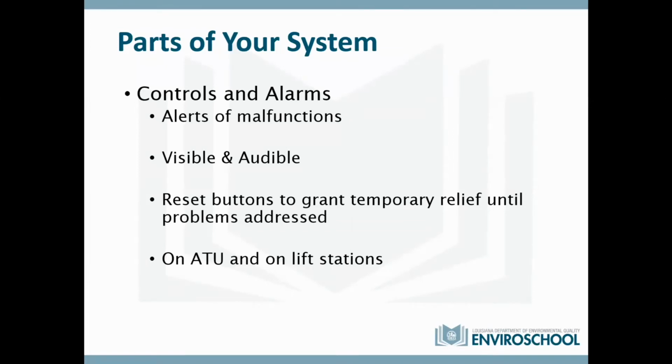Don't just ignore them. Some systems actually have lift stations on the other end of the treatment side to get the treated effluent to a sprinkler system. For the most part in Louisiana, I think they're used for sprinkler systems, but they could be used to go to a mounding septic, a drain field, or just to get it further down into a ditch.